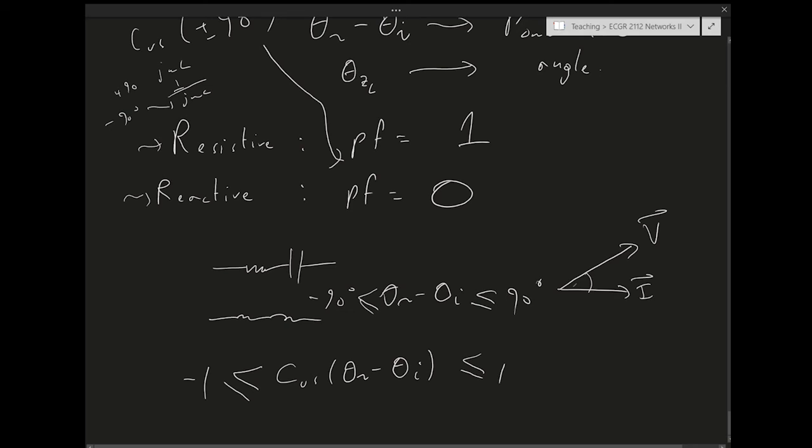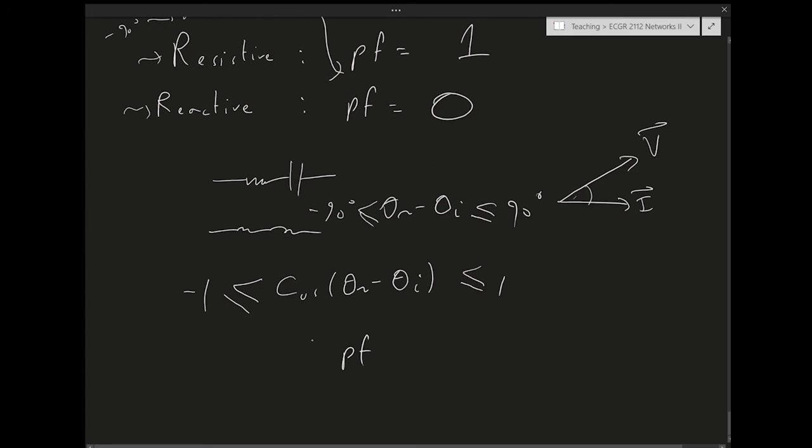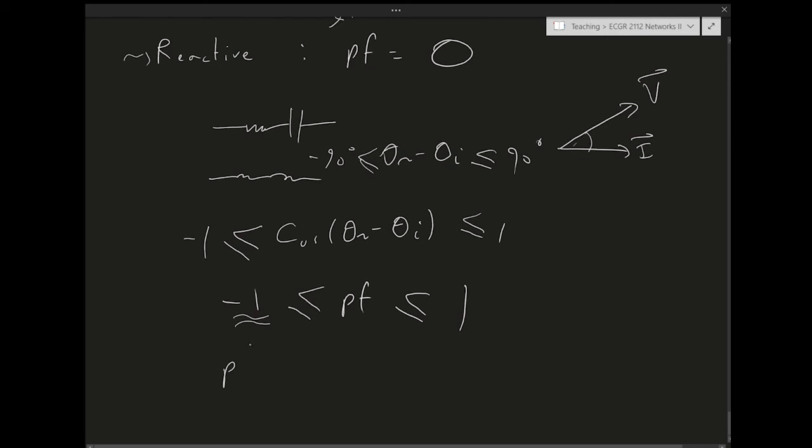So in the case where we have mixed elements, resistive and reactive components mixed together, the power factor is going to be between minus 1 and 1. Okay. Typically, we don't give negative power factor. Typically, we just give positive power factor. But then we say, right? And there's something curious here, actually.